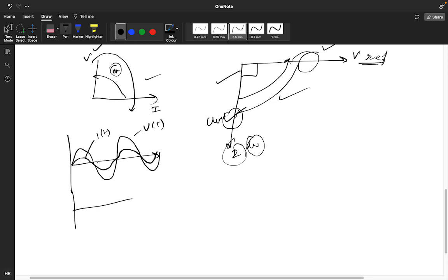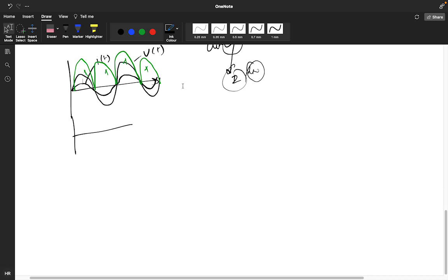So that's why we were getting positive only. Negative times negative is positive, and negative times positive gives zero, so we get positive power only. So in a resistor all the power was coming as positive only. But if you see for an inductor, the case will be different. How so? Here the lagging concept is coming.